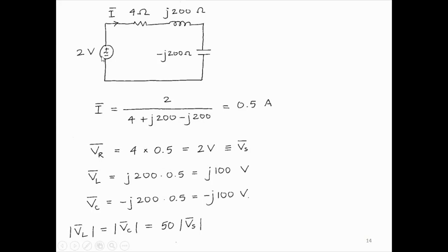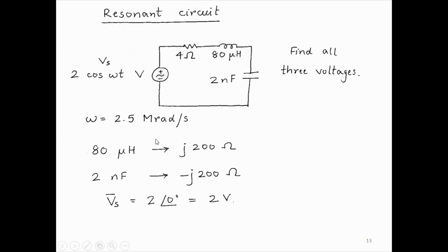The other thing that has to be done is that there are, of course, a zillion signals of different frequencies floating around in the air, and so the mobile has to distinguish the signal it wants, the signal on the frequency you are talking on, from all the other frequency signals. So this resonance circuit gives a 50 volt output at that particular frequency. At 2.5 megaradians is the frequency at which the inductor and capacitor impedances are equal. At no other frequency are they equal.